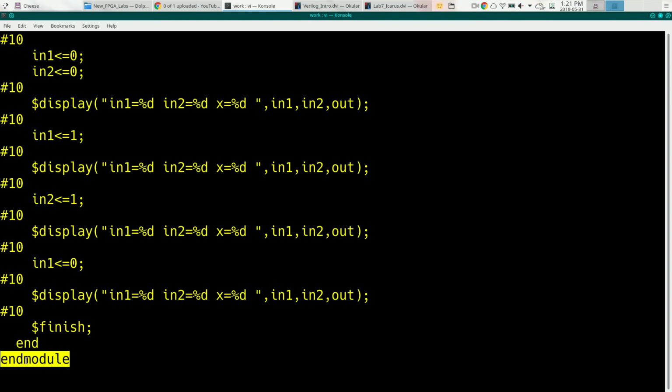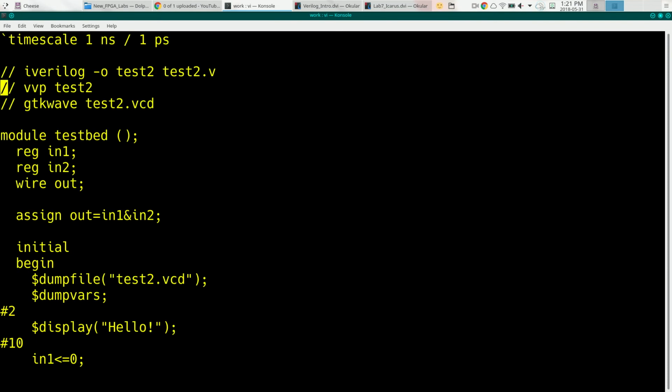So if that made some sort of sense, that's good. If it made very little sense, that's not surprising. But you can kind of use this, or the things in the handout, as a template. And you can change your actual Verilog. If we do this to simulate an AND gate, and now you want to practice, turn this into an OR gate. Assign out equals in one pipe in two. Or make it an inverter, out equals exclamation mark in one. And play around with it, get some practice doing this. But let's go ahead with an AND gate.